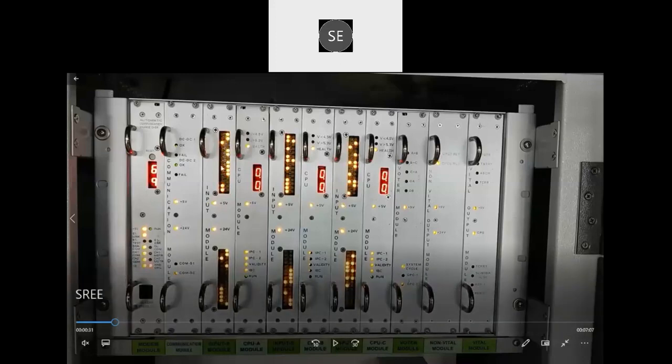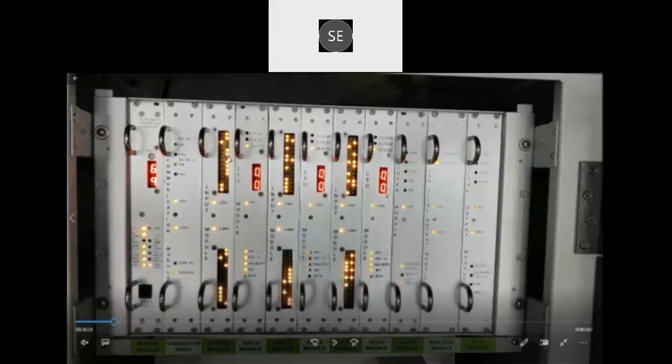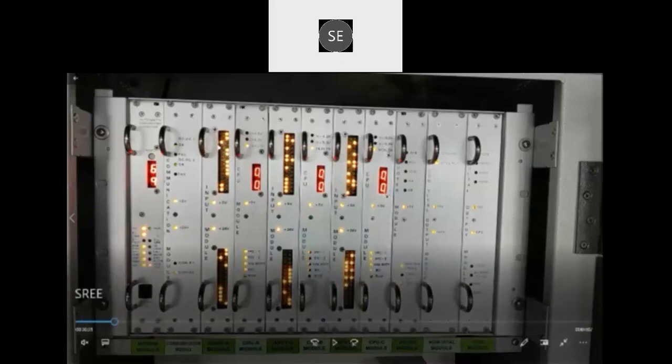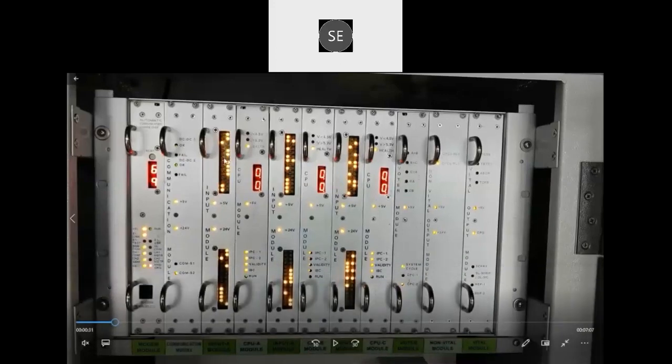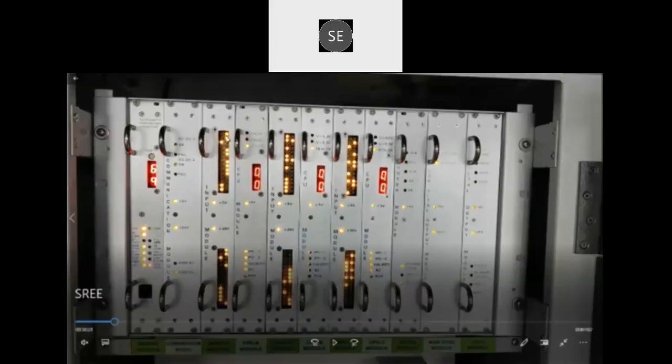As we are wiring both contacts to detect bi-state failure, we are wiring both front and back contacts of each button, each relay, each key, so that it is easy to detect a bi-state failure. So all buttons, all keys, front and back contacts are wired to the block instrument, so that status is shown here, whether it is closed or not closed.